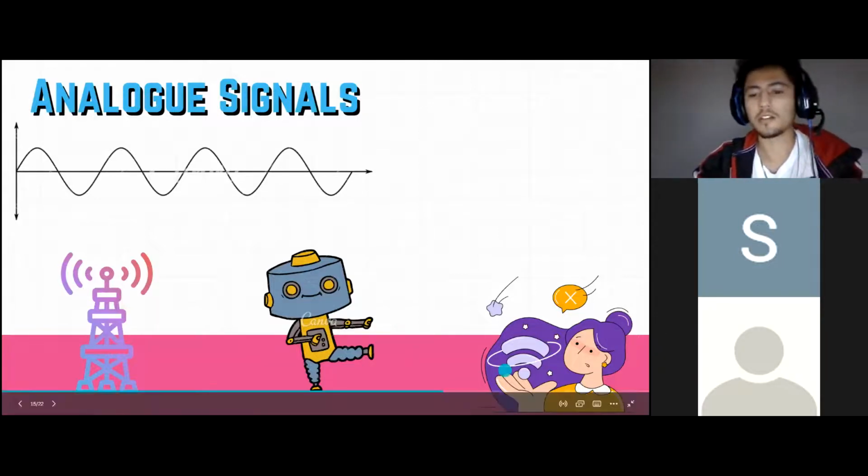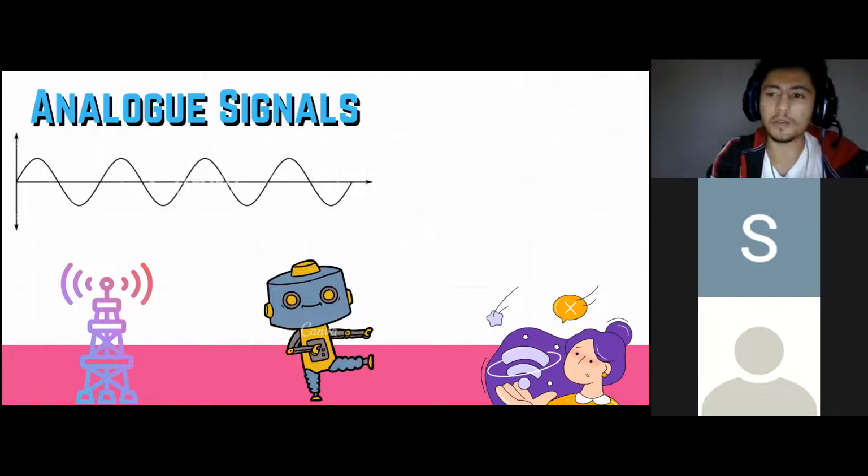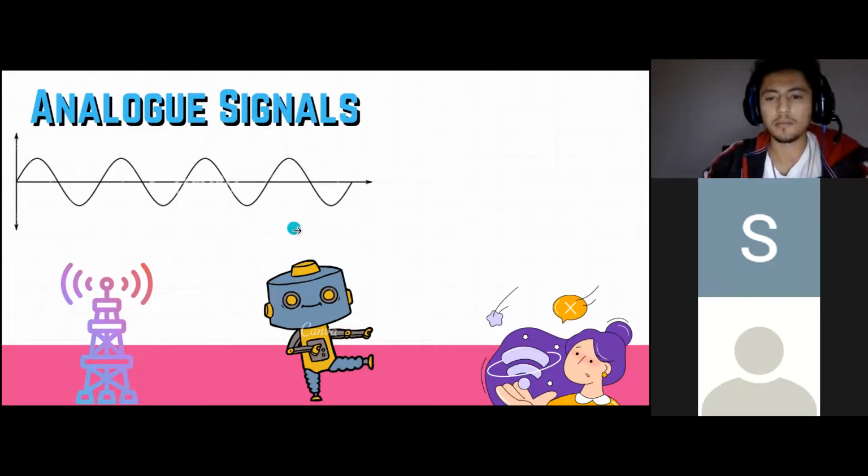Analog signals. Analog inputs and outputs are used by robots to either receive a value in the form of a voltage, which can then be converted to a number, or to send a voltage, which is converted and used by an ancillary piece of equipment to set or change one or more parameters.